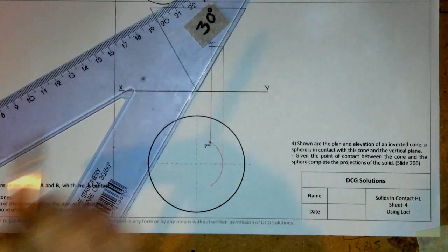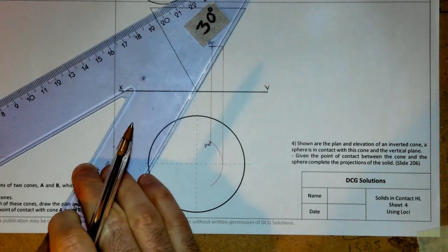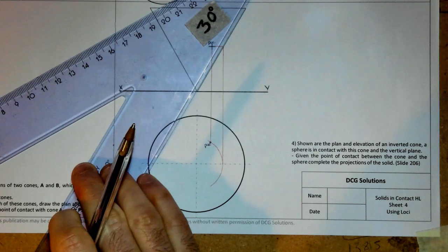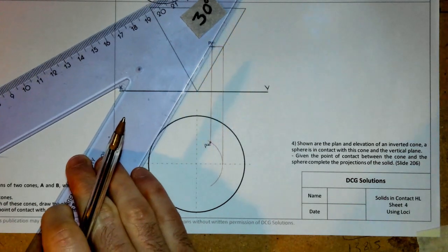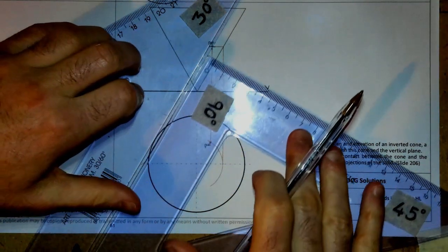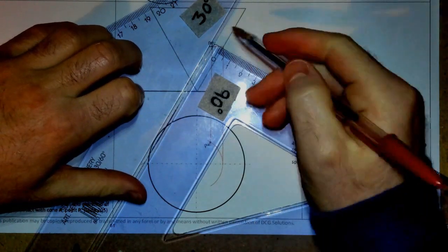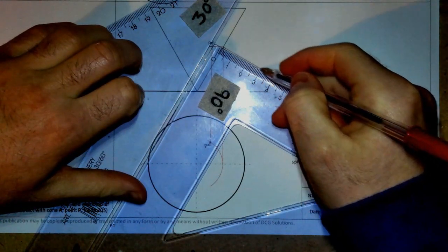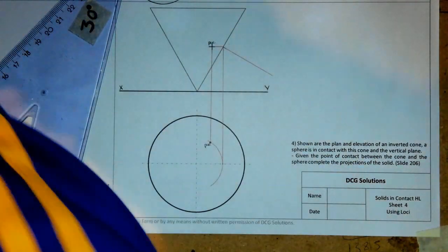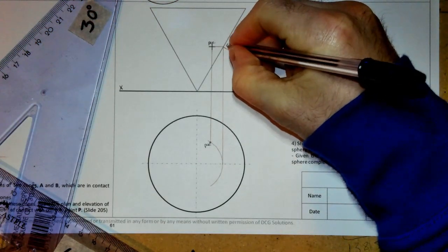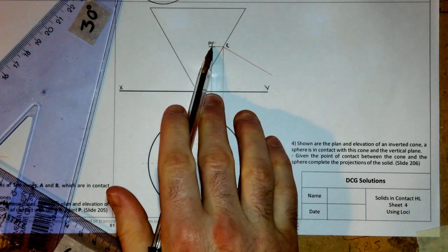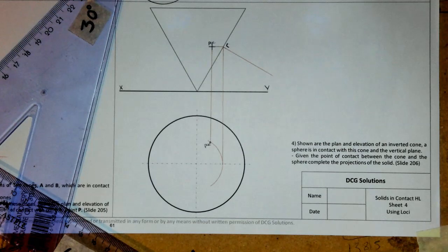So that's what I'm going to do first of all. I'm going to line up there with my extreme generator, like that. Pull it back, and somewhere out along there would be a ghost sphere that we want. The reason I use the extreme generator is because somewhere out along that perpendicular line from the extreme generator would be a ghost sphere of a radius that we want. I couldn't do it from the point of contact because that's not in the correct position to get the perpendicular line from the extreme generator.